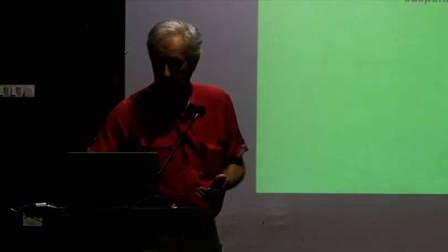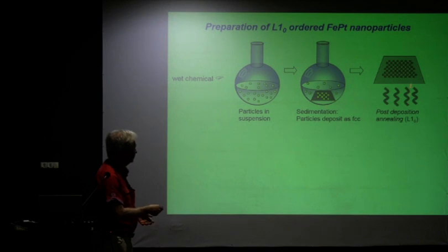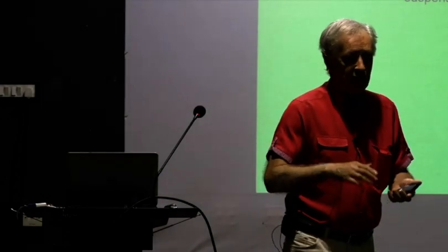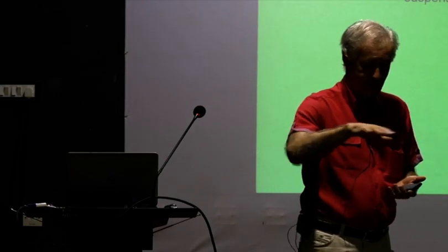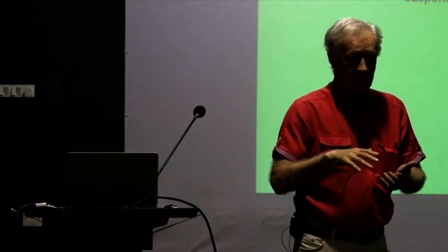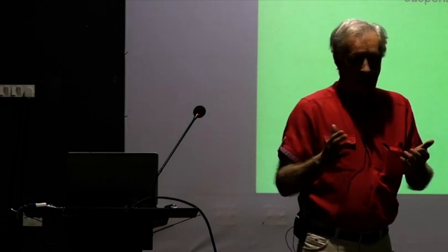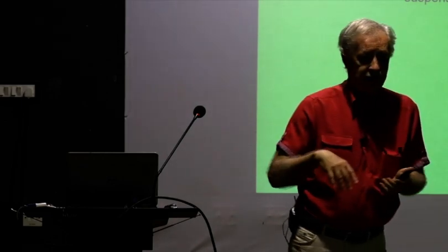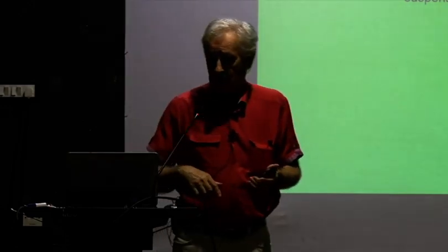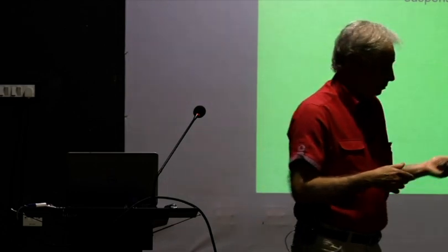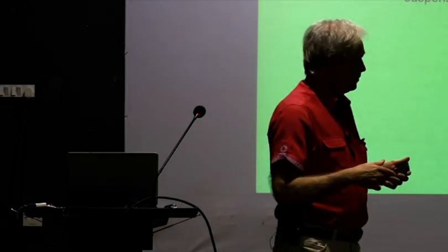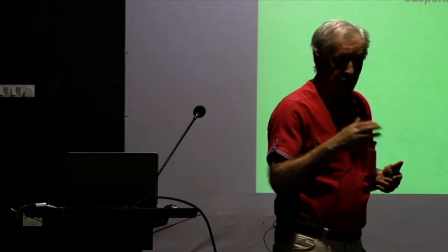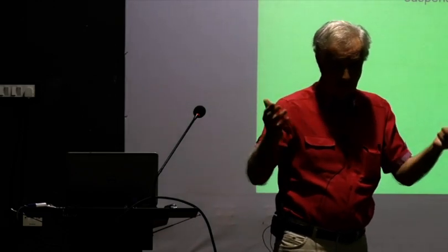And so in the wet chemical method, if you have your particles deposited, then you have to do some kind of a post-deposition annealing on this. Now, post-deposition annealing means that your particles have come onto your substrate, it's wet chemical, you probably got other chemicals and things like that, and then you anneal it, and it could be a mess, because you've got the substrate to worry about, you've got the leftover chemicals to worry about. It's not clean, but of course, in quantity, if you could use this method properly without getting all the undesired impurities, then you have a good chance of making large quantity particles.